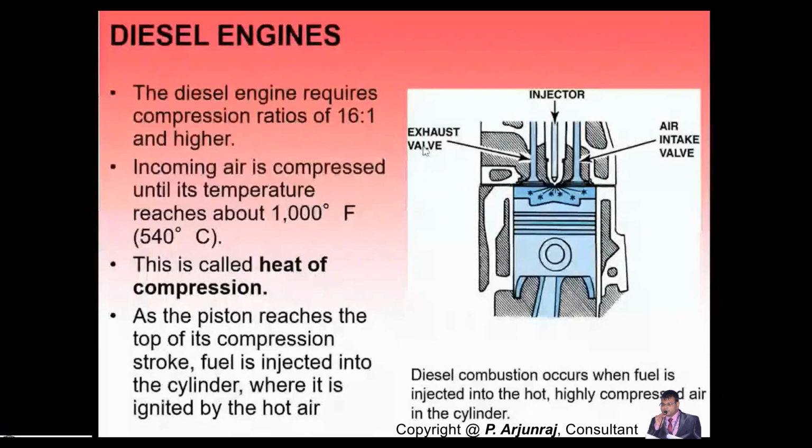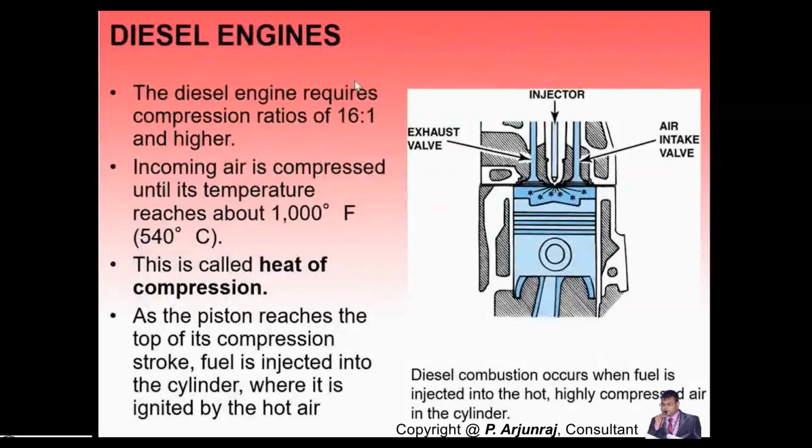Here, with respect to the diesel engine, what is important is that diesel compression ignition occurs when fuel is injected into the hot, highly compressed air in the cylinder. And again, you see here the compression ratio of diesel is higher than petrol, having 16:1. It can even be higher than this also.